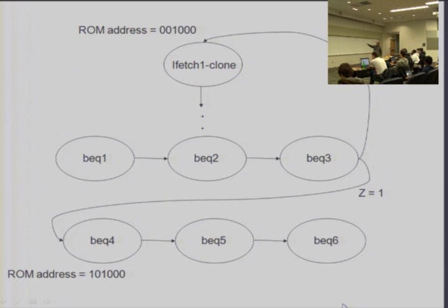The first branch is saying, if this particular instruction, branch unequal, if the equality fails, right, then you simply go back to fetch. On the other hand, if the equality is successful, then you modify the PC, and then you go back to fetch, right? So these are two different things that we were doing, and we're basically able to effect the two-way micro branch.